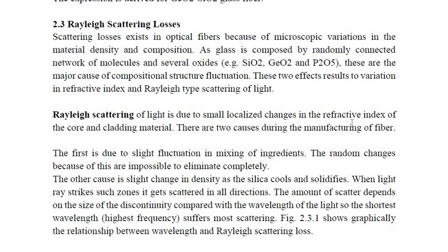So refractive index plays a very important role in scattering. The first cause is slight fluctuation in mixing of ingredients. The random changes because of this are impossible to eliminate completely. The other cause is slight change in density as the silica cools and solidifies. Since it is made up of glass material, it is maintained at a particular temperature, so first it gets cooled and then solidifies.